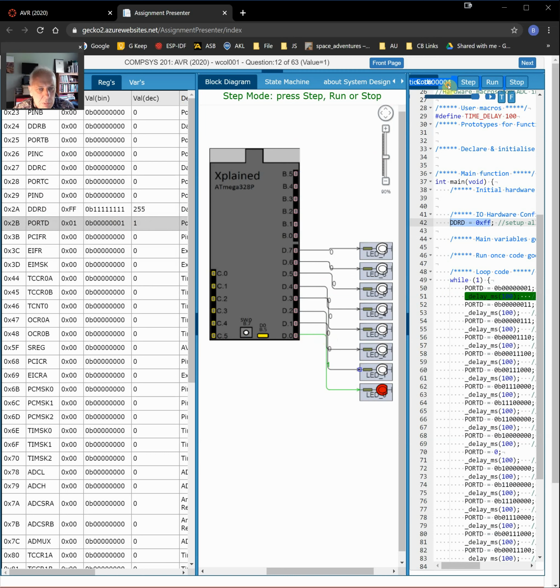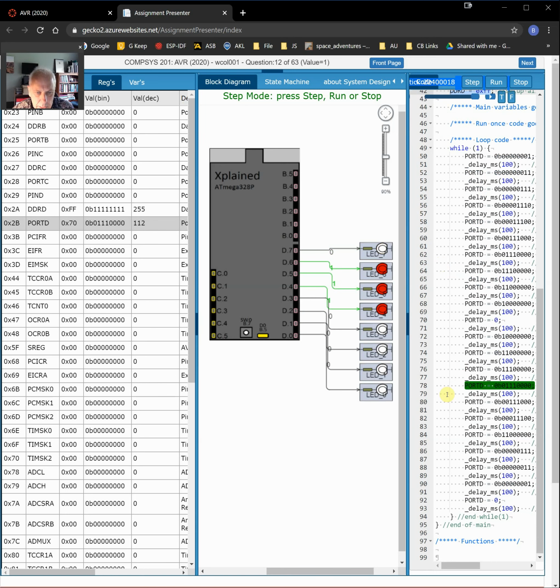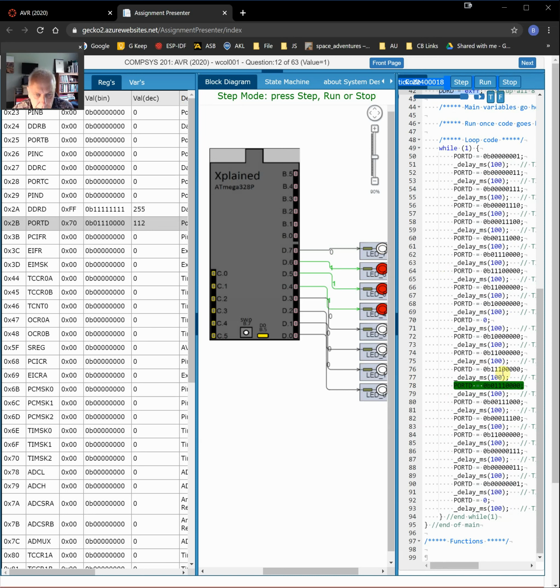And as we go through this program, you can see that it's going to just change the position of the pattern by actually turning on and off sequences of LEDs. Now, as I step through this program, you're going to see that there's an error at one point. So this is correct. It goes to one LED, then they go off. One LED comes back on, 2, 3, and if I'm scrolling down, you can see the pattern is actually fairly obvious in these 1s and 0s. 1 here, 2 here, 3 here, 3 here, 3 here.